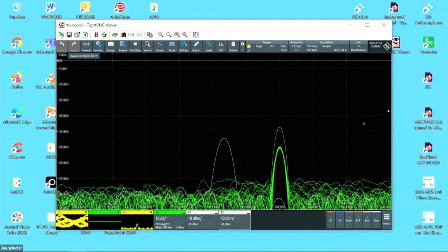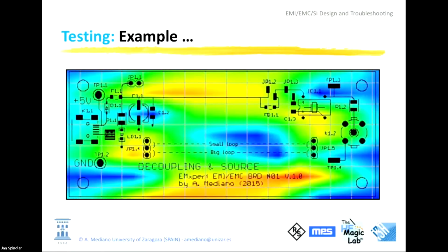You see, oh, sorry, something like this. This is the power supply input. This is the USB connector. Here is the component for the clock. Here is the ferrite bead. Here is the capacitor close to the integrated circuit. You see here the VCC line, and the ground line is not visible because it's on the other side of the PCB. So I have this loop.